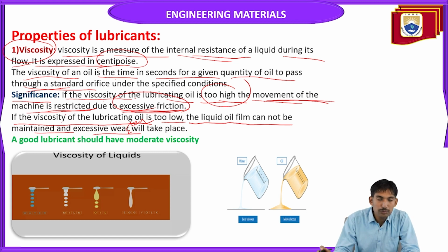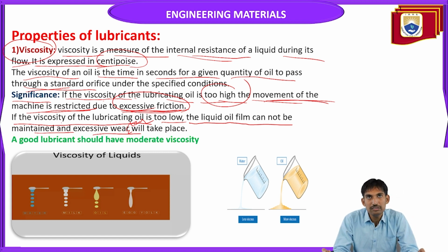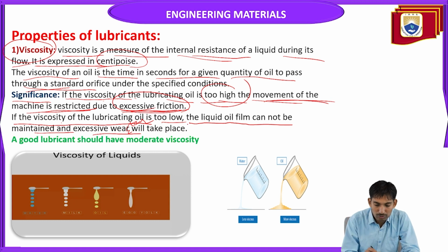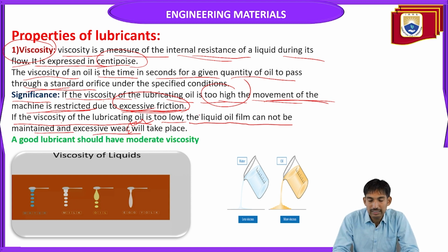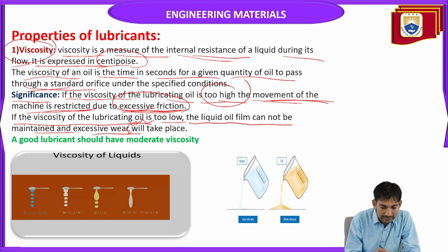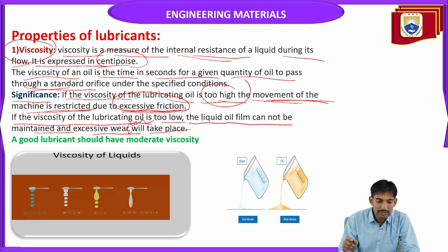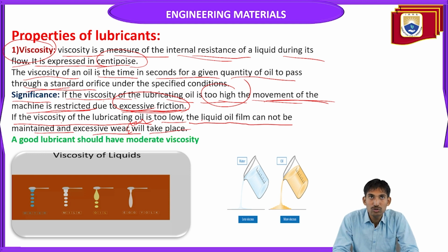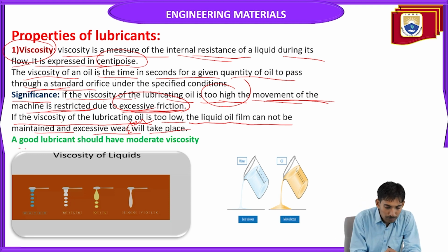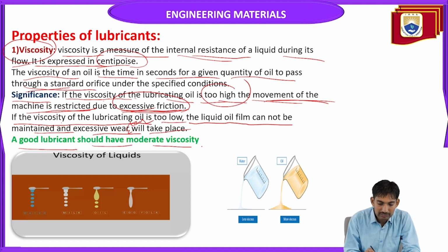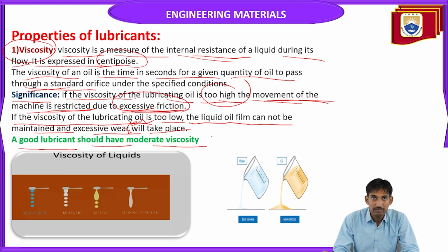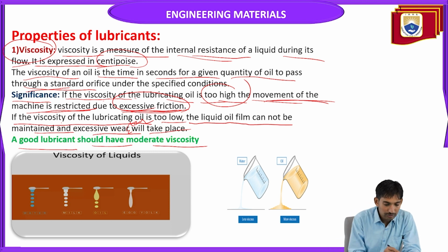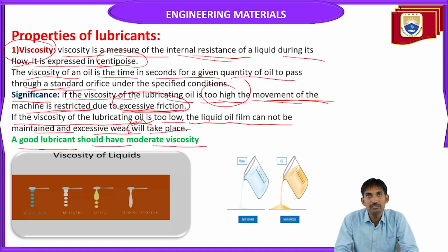If the viscosity of the lubricating oil is too low, the liquid oil film cannot be maintained, and excessive wear and tear will take place. A good lubricating oil should have moderate viscosity. It should not be too high or too low.